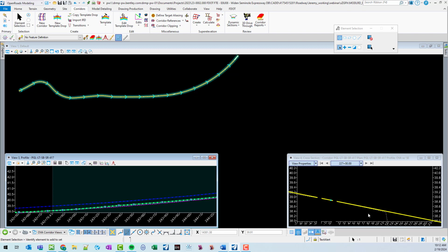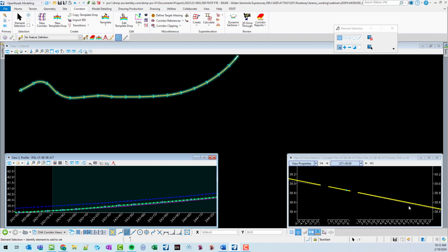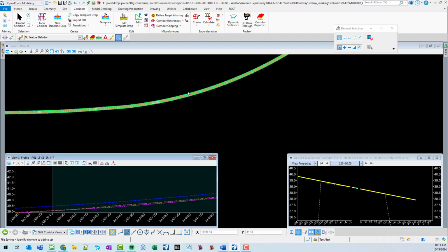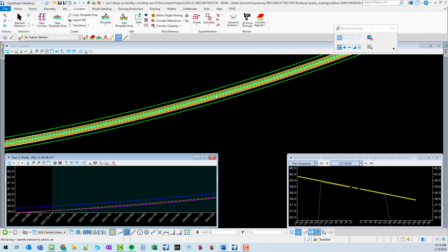Here we go. So using that profile, with this super elevation, we have a new profile, and here it is all above the dashed, the existing ground essentially. There's more to elaborate on that, but I'm just trying to go through this entire workflow. The next step is going to be creating a heat map to show, using this profile and this corridor, where we're above existing ground and how far we're overbuilding and such. So, yeah, I'll move on there.